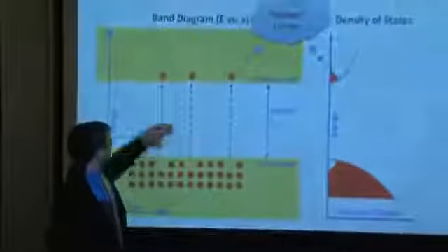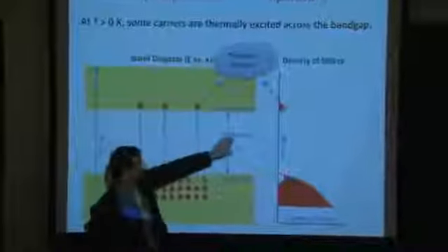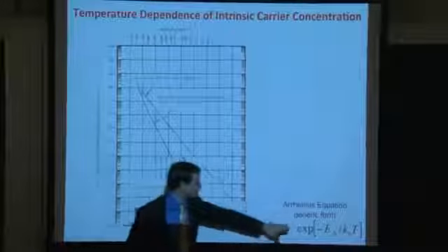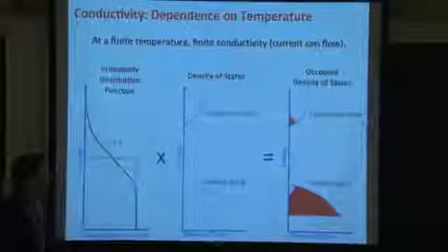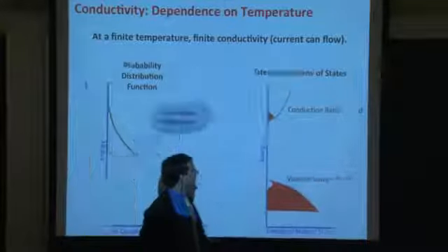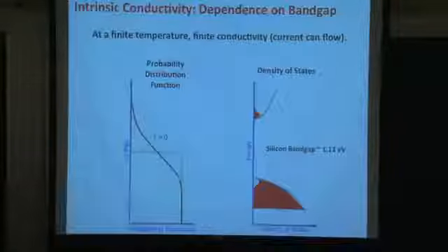because there's a smaller band gap, it's going to be easier for carriers to hop across because the band gap is smaller. Another way to look at it is, on the Arrhenius plot, you'll have a higher carrier concentration because your slope is smaller. Your activation energy is smaller. And as a result, if the band gap shrinks, you'll have a higher carrier density here in the conduction band. Let me show you that in pictorial form.